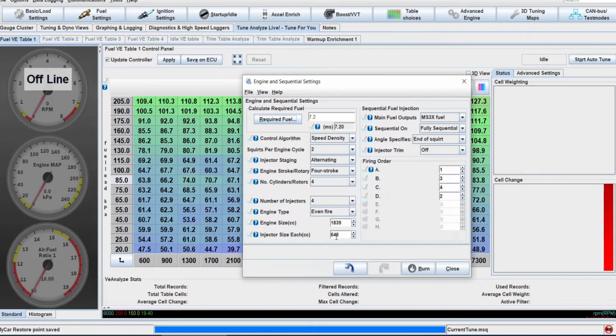So if you really want to run E85 and you want to do it like the OEMs, you need a flex fuel sensor. That's how the OEMs manage to deal with all these changing conditions, different fuels, different places, different temperatures, and it all seems to work magically. That's how they do it. So if you want to be like them, you need one of these sensors, and you can do it, and it's not very expensive.